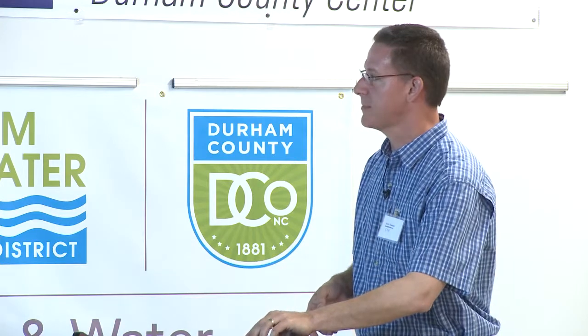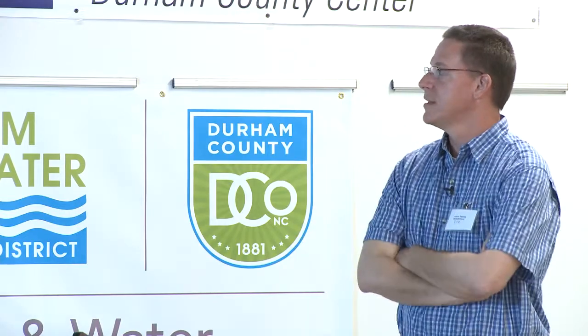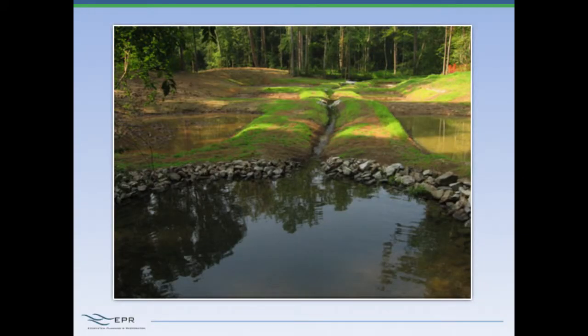We talked a little bit about this one yesterday. This is phase 3, which was the wetlands. The issue that came up on this one, I believe it was Kurt that talked about it yesterday, was that it ran into a permitting issue because the existing channel that was there, which was highly degraded, was considered perennial up to the point of the discharge pipe that leads into this. The comment that came back was, well, you can't put a wetland in a jurisdictional stream. You have to maintain a jurisdictional stream.